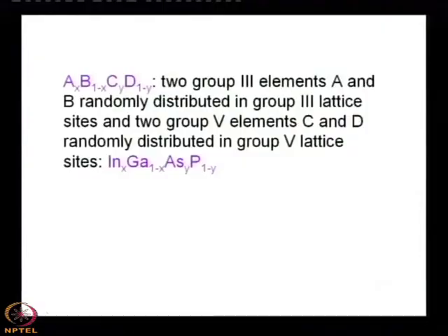If you dope silicon with p or n type, the band gap of silicon does not change. Similarly, if you dope say cadmium telluride or gallium arsenide or indium phosphide, the band gap will not change. The number of electrons or holes will be different during doping. So, I am not talking about doping, it is related to band gap engineering, where new materials are formed to tune the band gap for a particular application. Say for your fiber optic communication, you need 1300 nanometer or 1550 nanometer sources. So, you have to make a new material with such a composition so that its band gap will be matched.